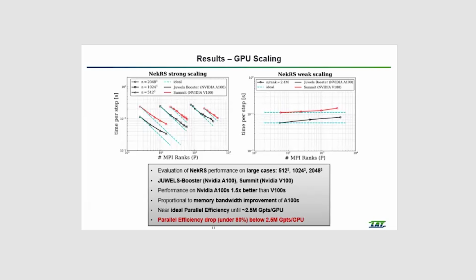And the results indicate an asymptotic convergence by increasing the resolution, of course. And I want to say that the simulation of the 2048 cubed, so the largest case, was not previously possible with NEK5000, and that was only made possible and achievable by the use of NekRS on the HPC architecture.